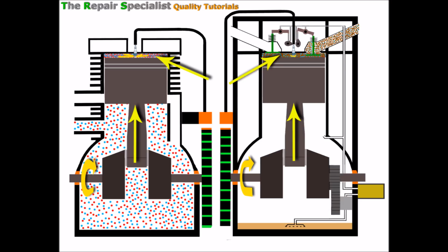We know that the spark on the 2-stroke is going to result in combustion again, and we've also got the spark on the 4-stroke, even though it doesn't need one as it's on the exhaust stroke. It sparks because of the magnet passing the coil, so it'll spark on every revolution of the crankshaft, every time the piston's at top dead centre, whether it's a power stroke or an exhaust stroke, and it's neither a detriment to the engine nor an advantage.